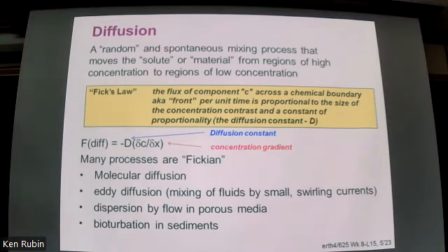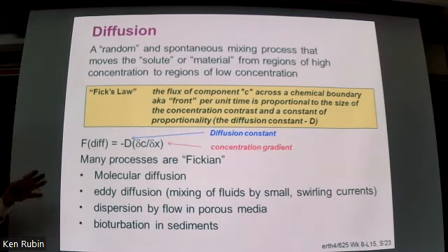When we talk about composition, diffusion is a process that happens at a molecular level, right? And the presumption is that, for instance, with diffusion in a fluid, the fluid is also not moving. When the fluid moves, that's advection. And in many cases, in fact most cases, both those things are happening. But we have to try and separate out the processes. And we'll look at some pictures of that in a second.